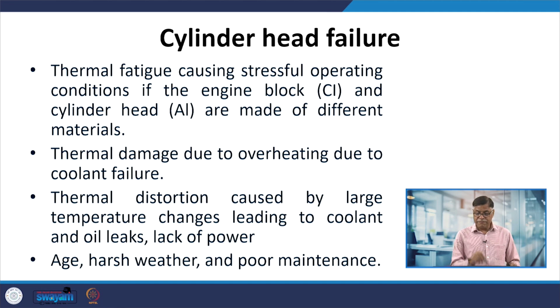As I have said, dissimilar metals means the engine block is of cast iron and the cylinder head is of aluminum. The heating and cooling cycles experienced by the cylinder head cause thermal fatigue. So, thermal fatigue creates very stressful conditions if different metals are used for making the engine block and the cylinder head, and that can promote cracking.